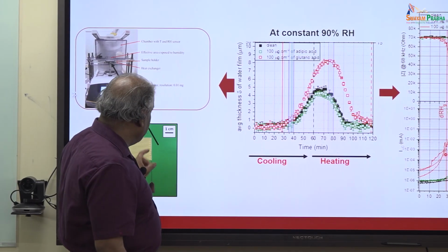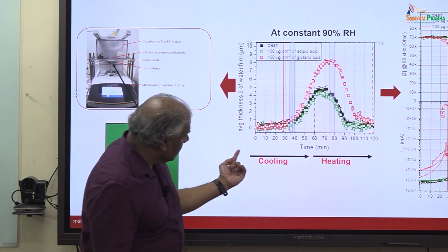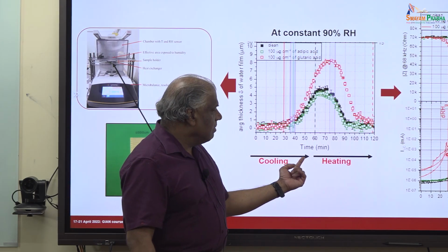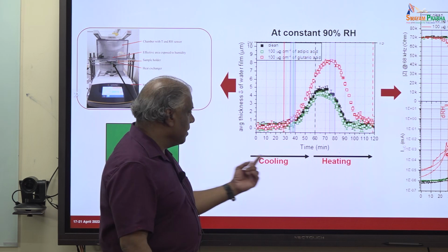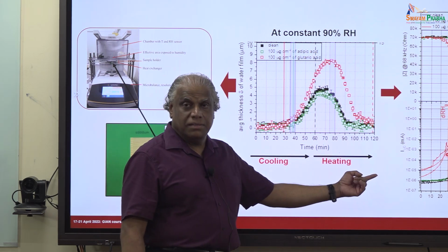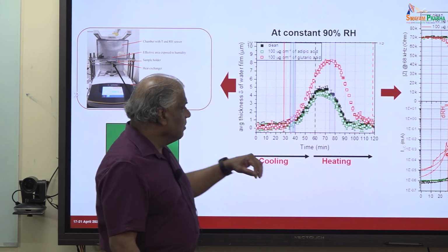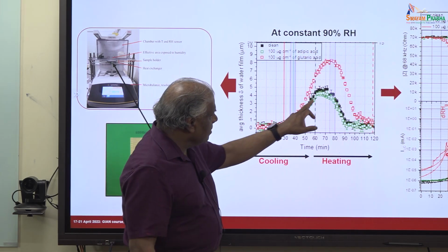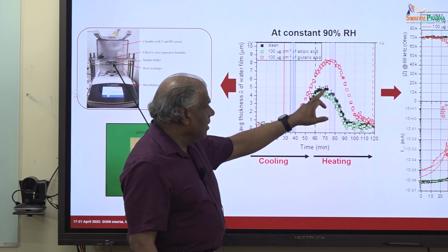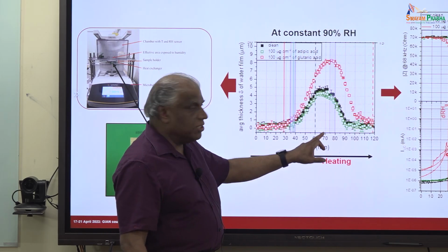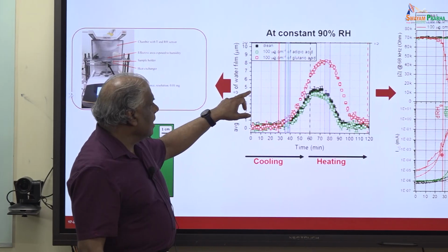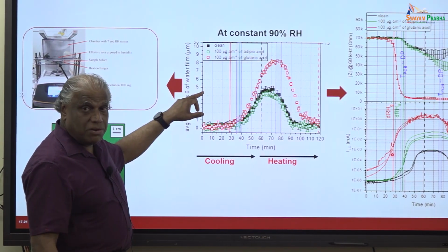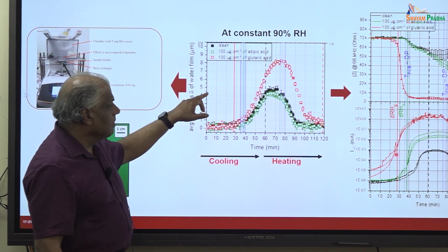Now we do this experiment, we cool down the substrate. So you can see here this time cooling. Then once the water film is formed, we heat to evaporate that. So you see the effect here. One is that if you have a clean surface, in a full condensing condition, you form around 4.5 micrometers of water film. It's quite thin still, 4.5 micrometers of water film you form.